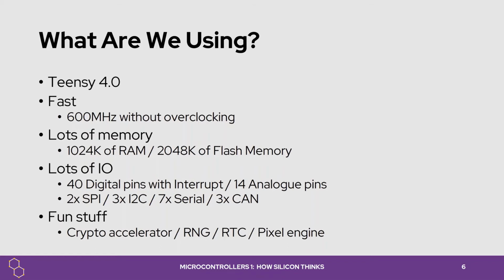The Teensy also has loads of memory: 1024K of RAM, which is 128 times what is available on the Arduino Mega 2560, and also 2048K of flash memory, which is 8 times what's available on the Arduino Mega 2560.